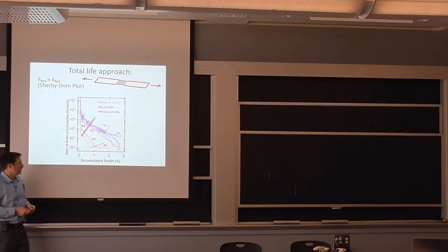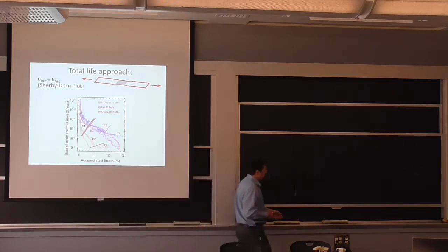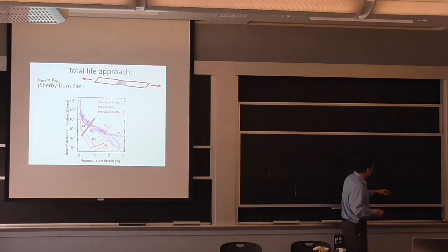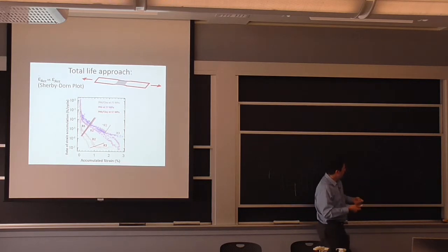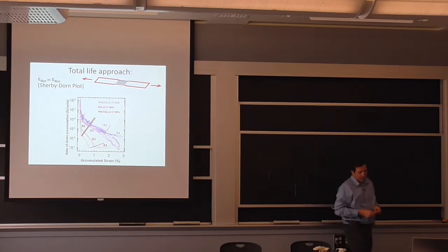And that is because even though we managed to organize the crystals here and reduce the ability to deform easily at the beginning, we did not change, for example, the length of the polymer chains. These were actually set to be about the same for the purpose of comparison. And those are the ones that govern the very long-term behavior, this viscous flow of one chain with respect to the other.